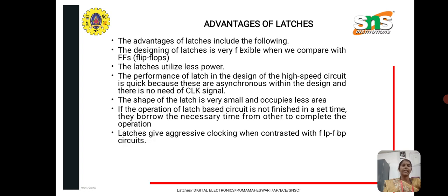The advantages of latches are that the design of latches is very flexible when compared with flip-flops. Latches utilize less power. The performance of latches in high-speed circuit design is quick because they are asynchronous and there is no need for a clock signal. The latch is very small and occupies less area. If the operation of a latch-based circuit is not finished in the set time, it borrows the necessary time from others to complete the operation. Latches give aggressive clocking when compared with flip-flop circuits.